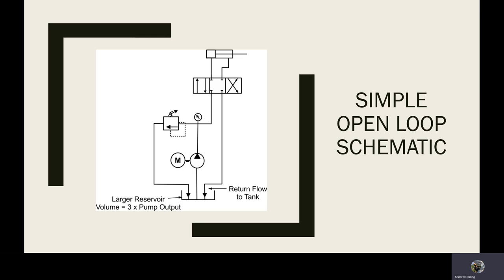The reason I know it's a pump is the arrow is pushing the fluid out towards this T or this X intersection, 4-way intersection here with a pressure gauge on top of it. This is a pretty standard setup, and if it's a motor, the arrows would point in that it's inputting power. So this is outputting the fluid flow, and the flow is flowing this way.